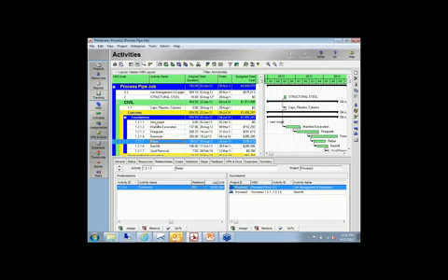Okay, so it's added this new scope. That new item we added in hard dollar showed up in the schedule. I can link it in wherever it needs to be linked. My machine excavation and my fine grading have those new durations, so those bars got twice as long as they were before. Right? And all of that pushes up to give us a new total duration. Everything's linked together, right? So now my job management and equipment duration is going to be longer. My escalations might go up because now the overall schedule is longer.